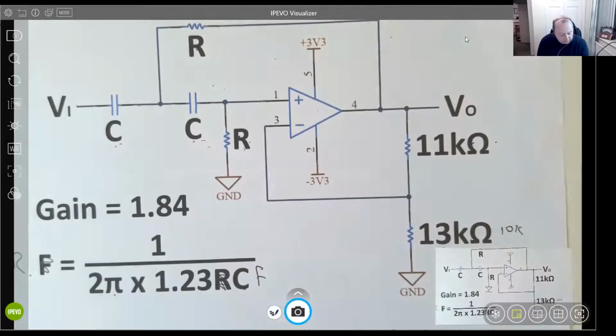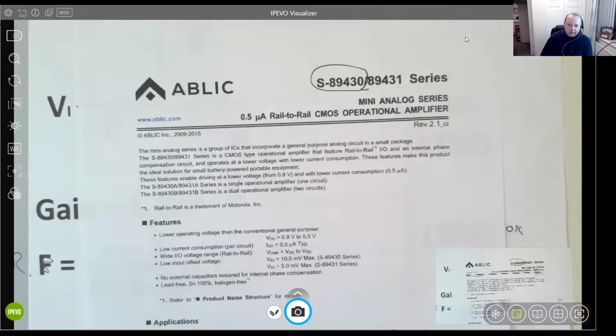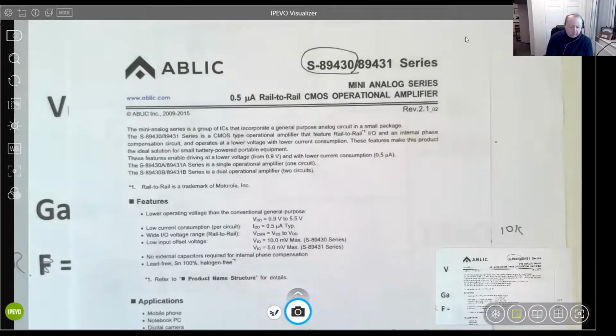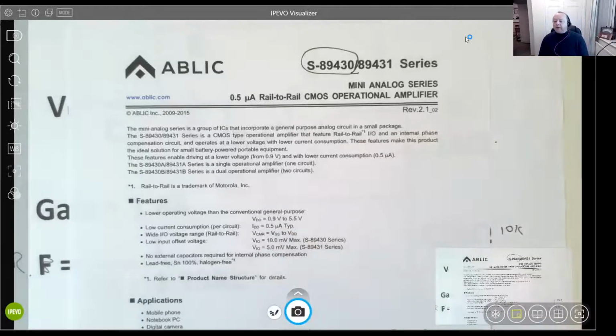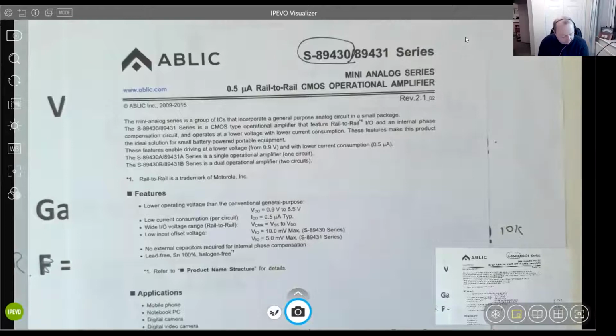I think if you have the values too high, I don't think it's so much close to being open circuit. This does depend on the device. If you take the old school 741, which is a bipolar transistor amplifier, you absolutely will not be able to use 1 mega ohm resistors. With this top one here, for example, which is CMOS, that's why it's down to just a few nanoamps, you certainly could get away with it, and no, it wouldn't be open circuit. However, if your resistor values are too large, whilst it will work in theory on paper, I think there's more chance of being susceptible to noise on the board, which is probably going to be a bigger issue than open circuit.